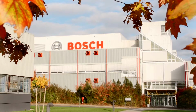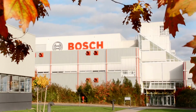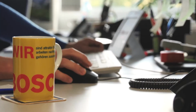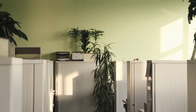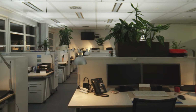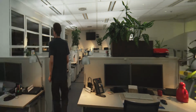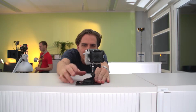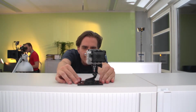From theory to practice: while converting an industrial building in Salzgitter, Germany, we had the opportunity to test the different effects of directed and undirected airflows. We are in a typical office room for 17 associates with an area of 160 square meters and an air volume of 600 cubic meters. Before and after the conversion, a fog machine sprayed the same amount of fog into the room for a period of 40 seconds. Two high-resolution cameras set up at the front end of the room recorded how the fog spread out. A number of action cameras were also set up to help record this process.